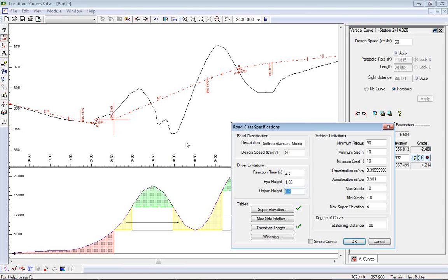There is another approximation in here. Again, it's just for the record. When the curve gets short enough, your sight distance is longer than the curve, and then you have to use a different equation to calculate your sight distance. We assume the curve is long when we calculate it, so again, we're being conservative.